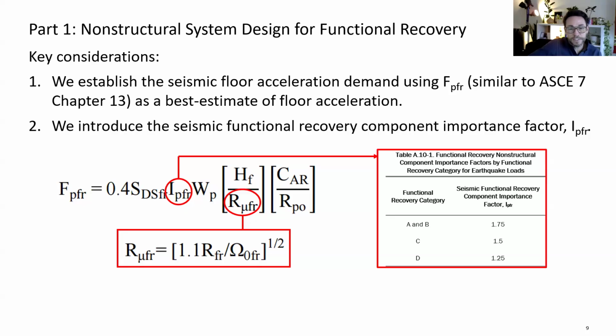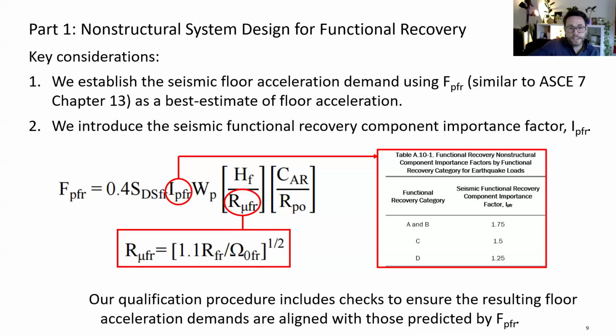Now, theoretically, this is captured in our provisions with the equation that you can also see on the side for RMUFR. But when we develop this qualification procedure for new systems, what we want to do is ensure that the peak floor accelerations associated with the proposed values of RFR and drift limit don't exceed the acceleration demands that are used in the design of non-structural systems. So in a nutshell, our qualification procedure, even though it's centered on the structural analysis of the system, it also tries to capture non-structural systems to ensure they're adequately designed to support the intended functional recovery goals.